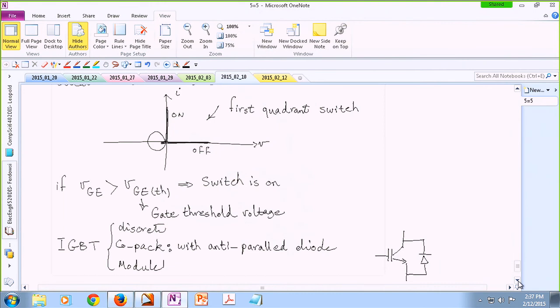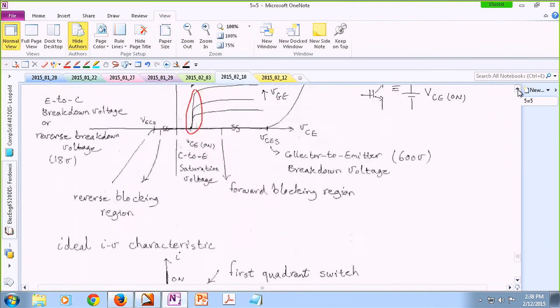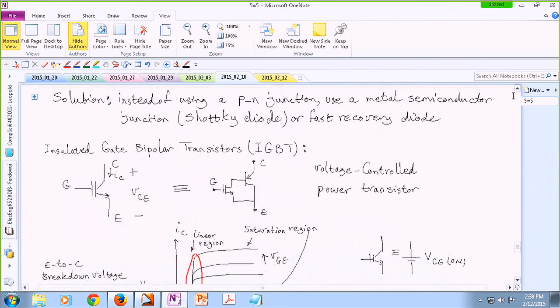When I'm using an IGBT as a switch, what's the input voltage I'm applying to that? Is it VCE? What do you mean by input voltage? For example, I'm connecting a battery to an IGBT. Okay. So the battery voltage will appear as a voltage across the collector and emitter. For instance, let's say you are using this IGBT to build a buck converter. Your input voltage in the buck converter appears when the switch is off from collector to emitter. Was that your question?